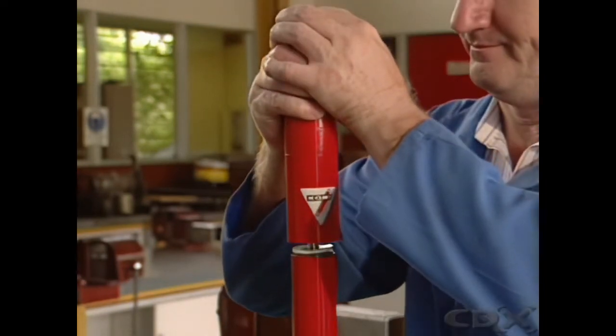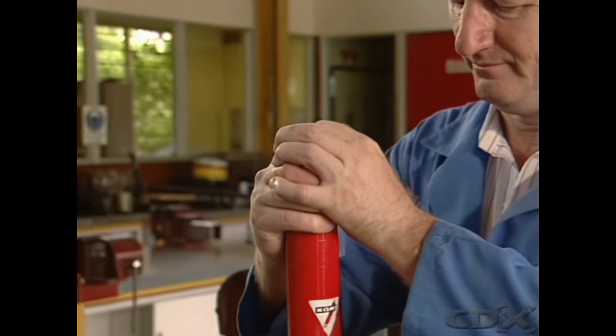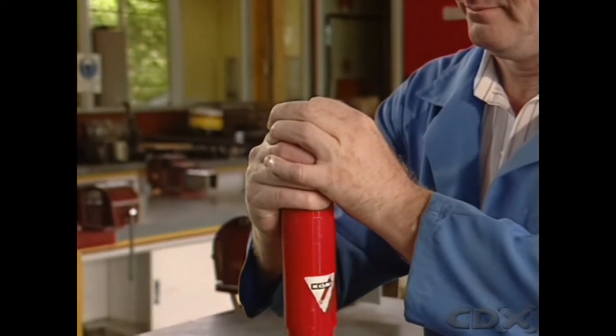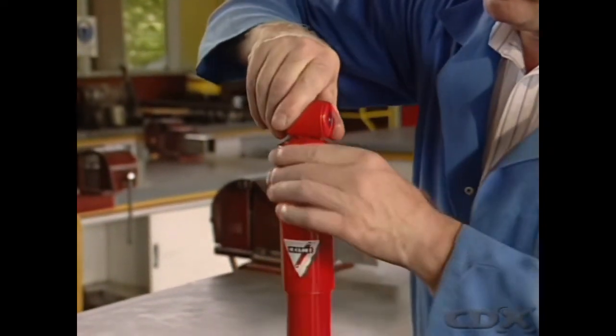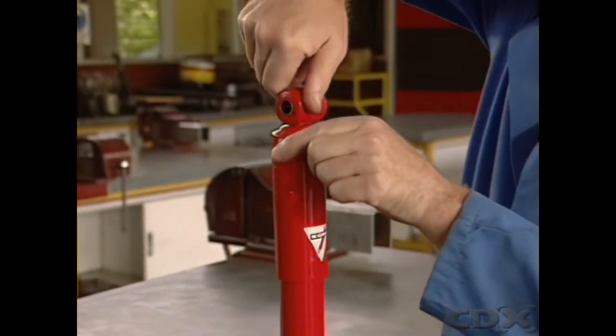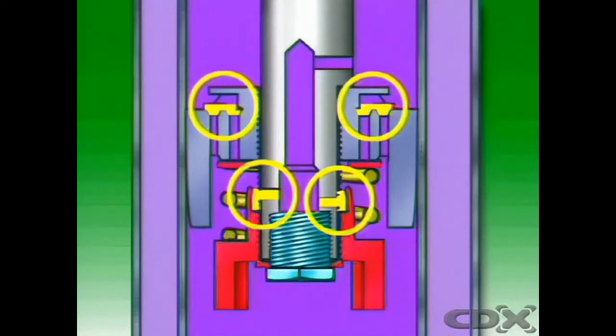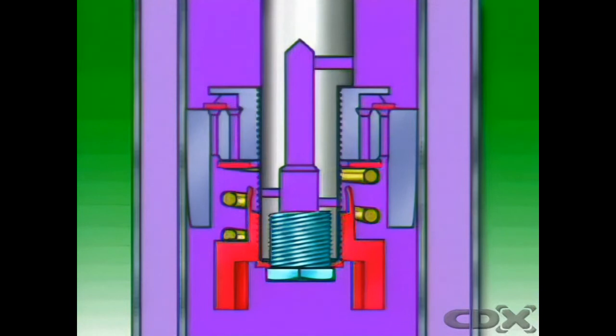Adjustable rate shock absorbers provide a means of changing the rate of dampening of the spring oscillations to suit varying road conditions or driver preference. This shock absorber has a manual external damper rate adjustment. The position of the valves in the piston can then be changed to vary the number of restrictions the oil has to pass through and to vary the force needed to open the valves.